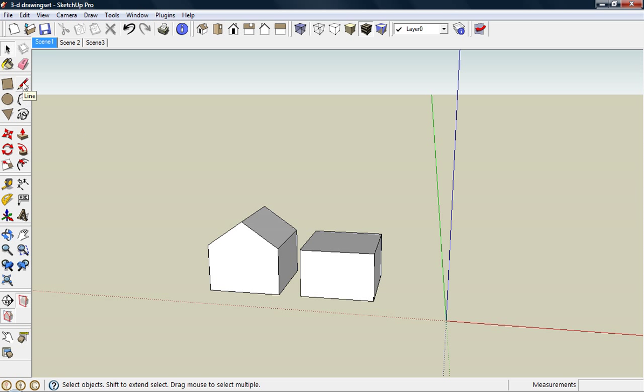Now that we know how to use the select tool, I'm going to create a new line here. I'll snap from midpoint to midpoint. I'll select that single edge with the select tool and then move into the move operation by pressing the M key. That's the shortcut for the move tool. I'll click anywhere on this line, and then as I move out, you'll see that I can adjust this shape by moving in any direction.